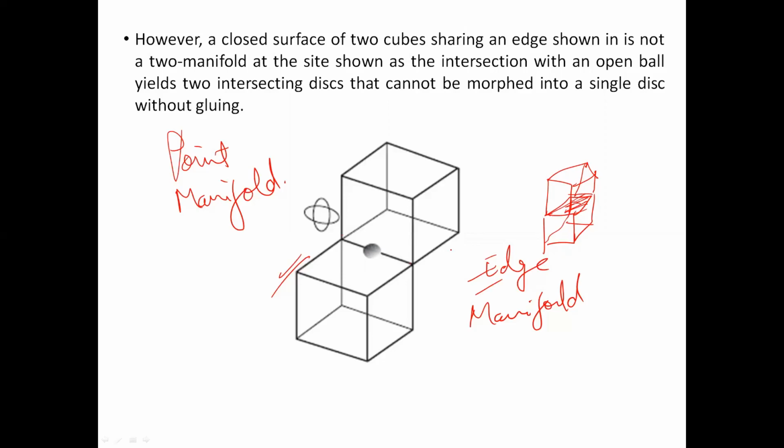So the intersection may have zero volume almost. No. The problem is that this plane and this plane are actually intersecting each other at this point. So what is happening is the two planes are actually intersecting each other. While when we read the definition of a CAD model, the curves or the surfaces have to be non-self-intersecting. But here what you are finding is that these surfaces are getting intersected.